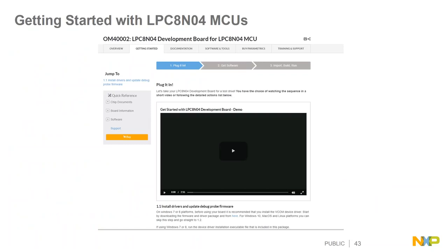If you want to know how to get started, we have videos. We have step-by-step guidelines on how to plug it in, how to install the drivers for the debug interface, and how to get the software. Where in nxp.com can you find that software? How can you import that board support package and use it, whether in MCU Expresso, Keil or IAR, how to import it, build it, and run it. In the board support package you're going to find examples and ways to start leveraging this LPC804 board, the LPC804 and the NFC and the Cortex-M0+. So we have you covered on those kinds of things.